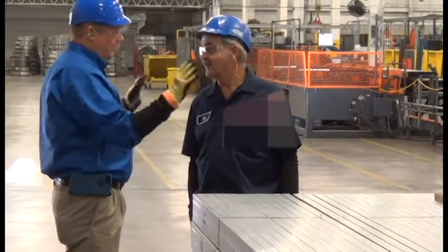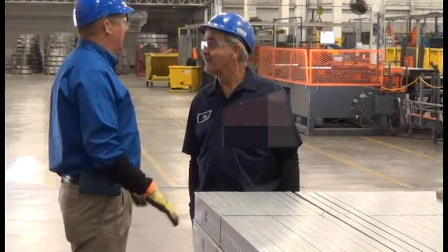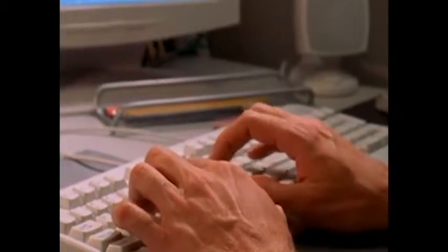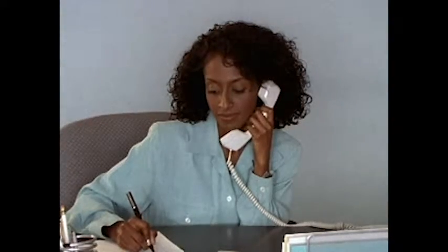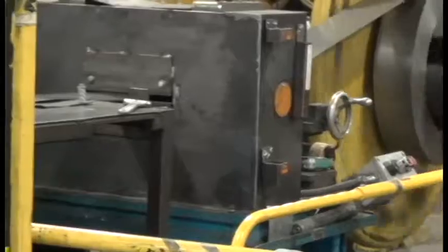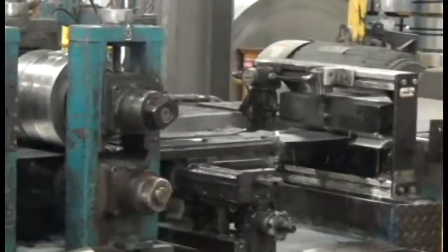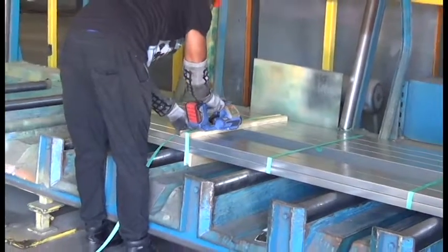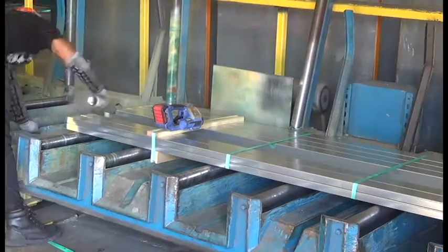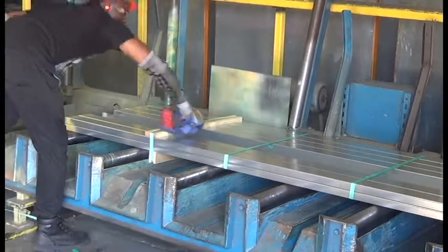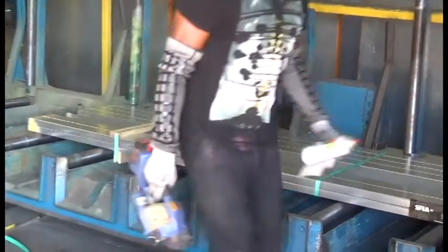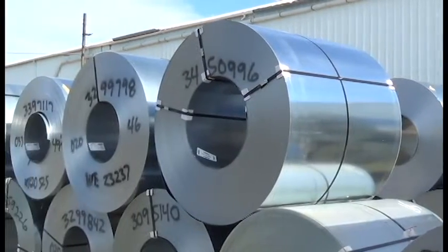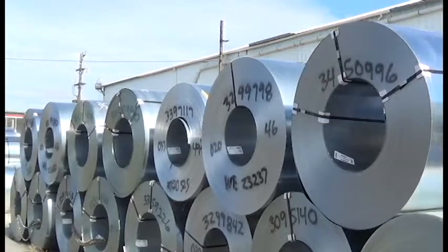There are several critical steps in the manufacturing process which affect the traceability of the product, starting with the ordering and receiving of the coil from the mill or supplier, followed by the roll forming of the stud or track, and ending with the final product marking and shipment. Remember, traceability refers to the ability to link that finished stud or track back to the original coil and supplier.